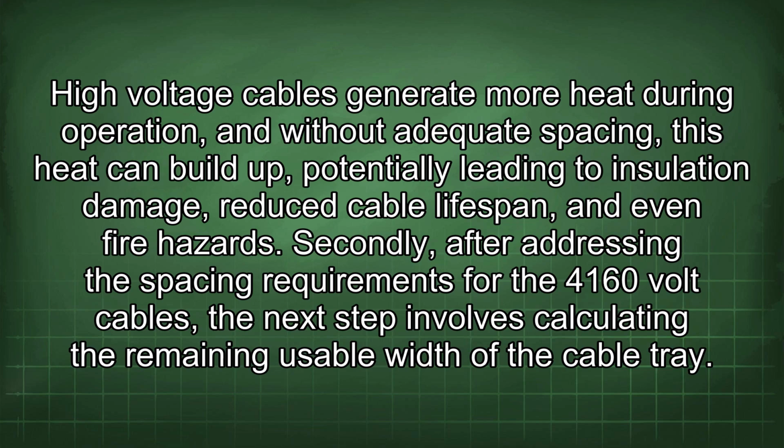High voltage cables generate more heat during operation, and without adequate spacing, this heat can build up, potentially leading to insulation damage, reduced cable lifespan, and even fire hazards.